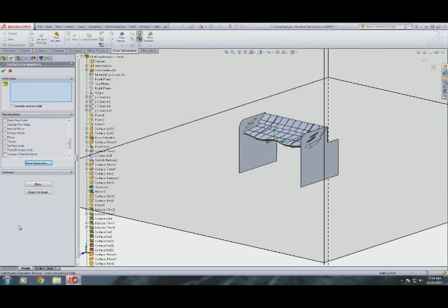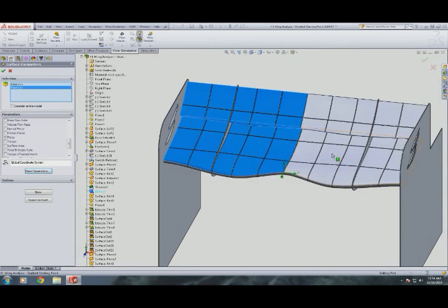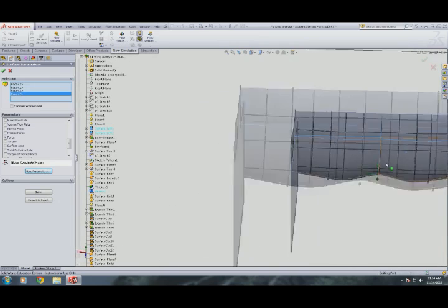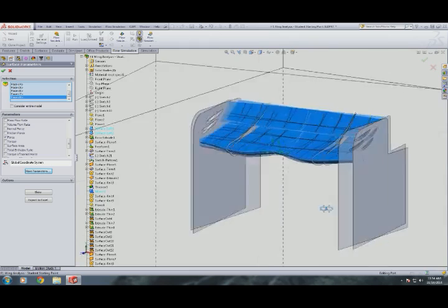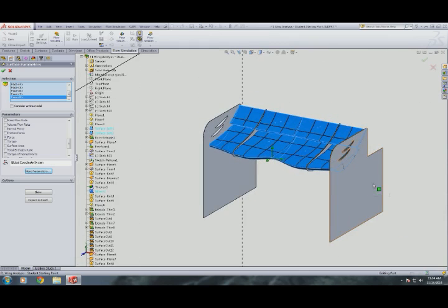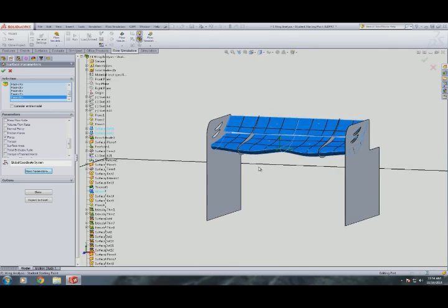Nice. Select. Let's choose the surfaces we want to integrate force over, so we can do this one, this one, this one, this one. And also getting the bottom side is important as well, because the low pressure there will actually help suck you to the ground a little bit extra. You could go ahead and click these end plates again, but like I said in class, the only forces that really matter are the ones pointing up and down.